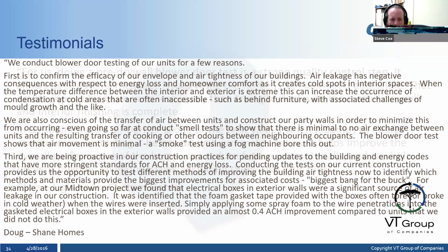Doug from Shane Homes writes, we conduct blower door testing on our units for a few reasons. First, to confirm the efficacy of the envelope and airtightness of our buildings, because air leakage has negative consequences with respect to energy loss and homeowner comfort, as it creates cold spots in the interior spaces. So cold areas that are often inaccessible, such as behind furniture, with associated challenges like mold growth and the like.